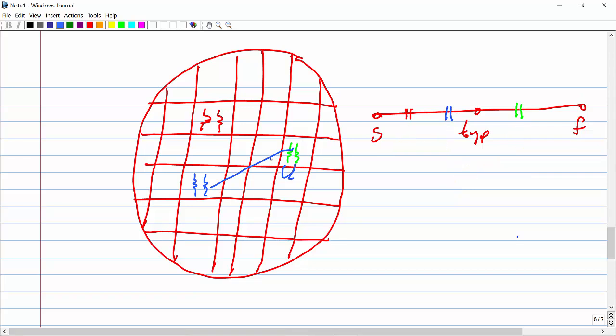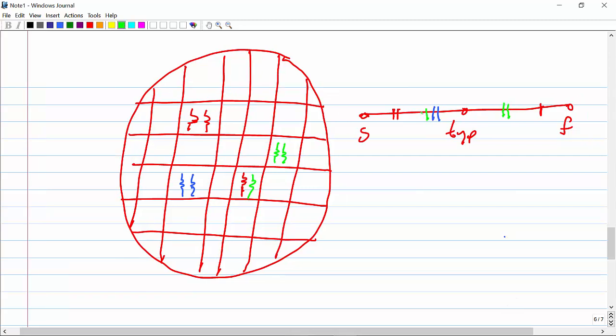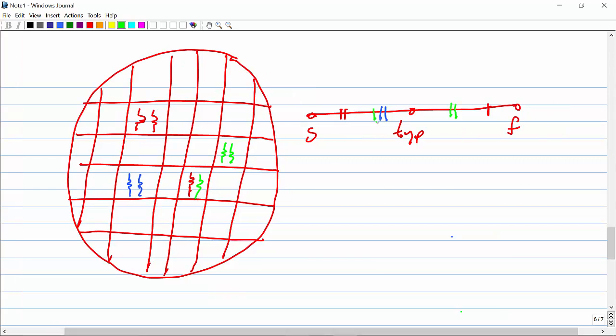The case that will never occur is that you get a resistor located here and another resistor located here. This will not happen because in the layout they are placed very closely, so there will not be this much process variation in an IC.